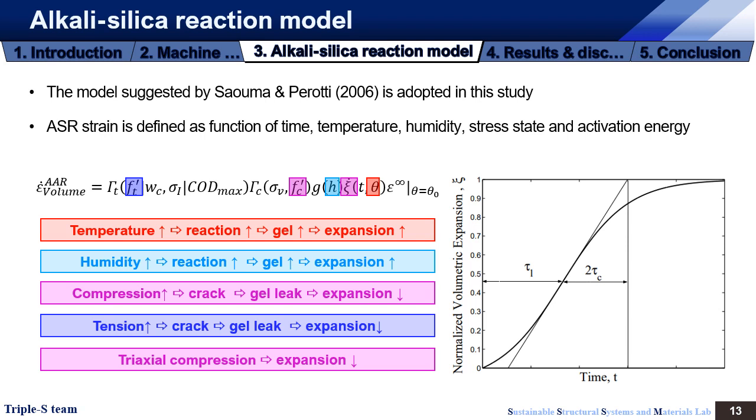There are many constitutive models for this reaction, but in this study we only considered the Saouma and Perotti model of 2006. In this model, the strain due to the alkali-silica reaction is defined as a function of time, temperature, humidity, stress state, and the activation energy.